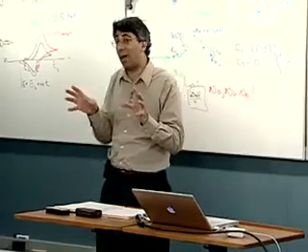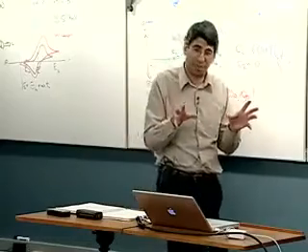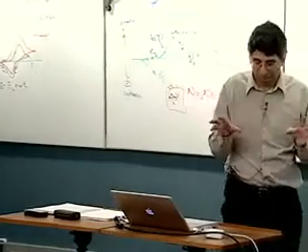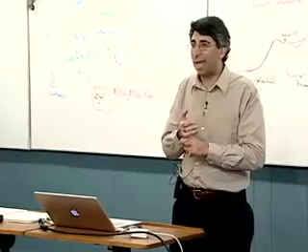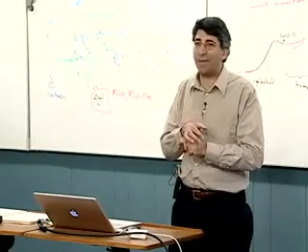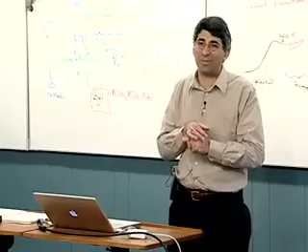That might be kind of obvious, but what about the potentiostat itself? There's a couple things you have to watch out for here. Number one is there are some potentiostats that will allow you to drive them faster than they're designed to be driven for some reason.